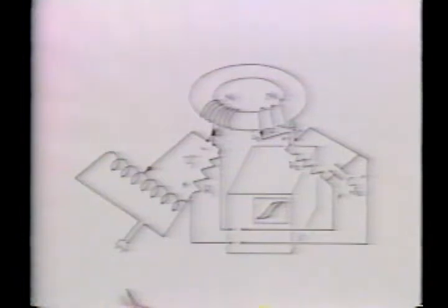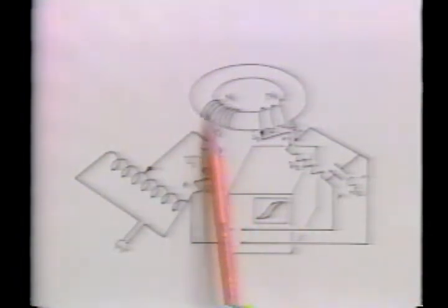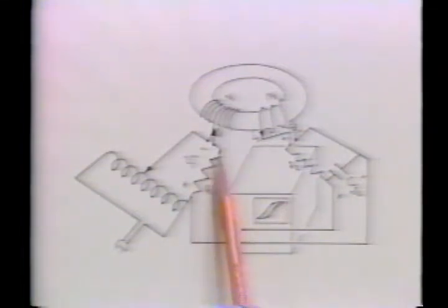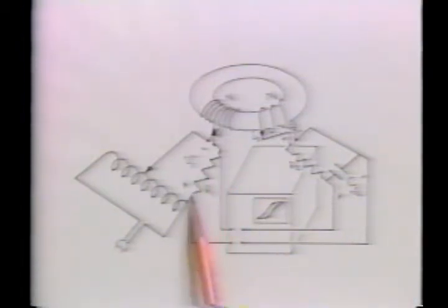The magnetic flux density is measured by means of a second sensing or secondary winding, also wound on the donut-shaped core. This coil is terminated in a high enough impedance that it carries a negligible current. Thus, the H field established by the current I of the excitation winding is unchanged. The flux linked by each turn of the sensing coil is essentially the flux density B multiplied by the cross-sectional area of the core. The flux linked by the N2 turn coil is then N2 times the flux linked by each turn.